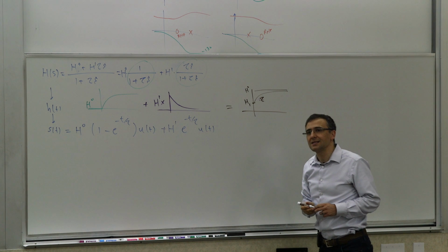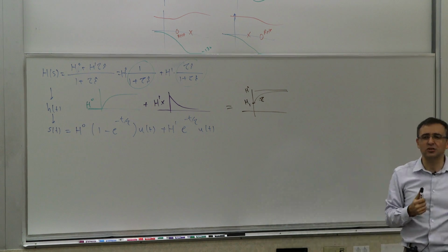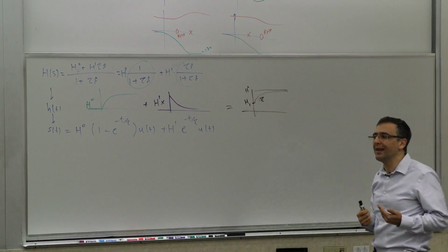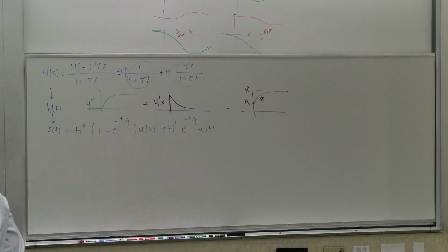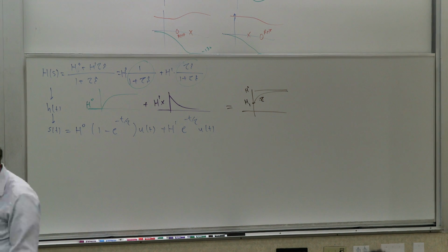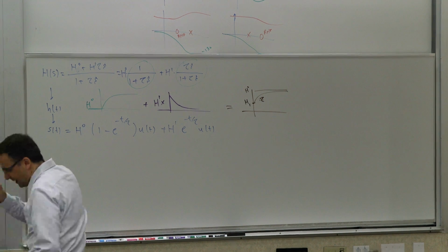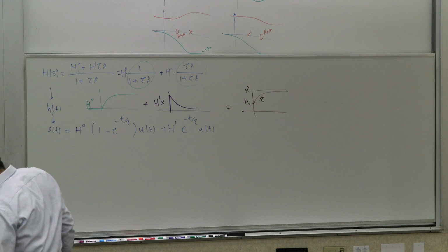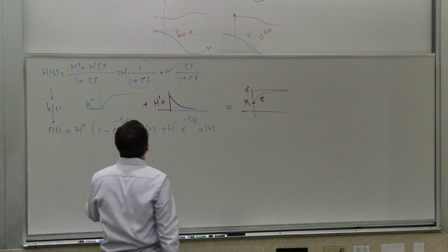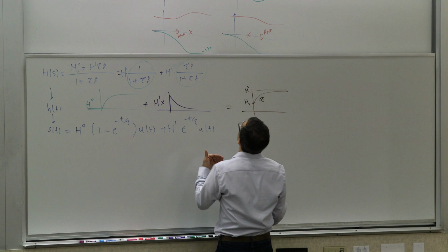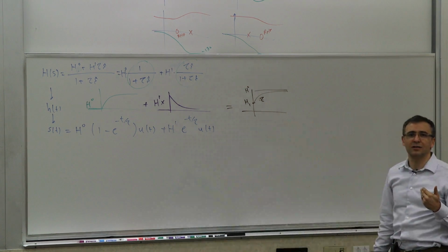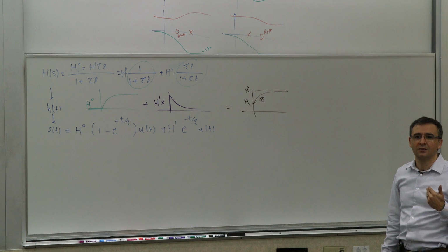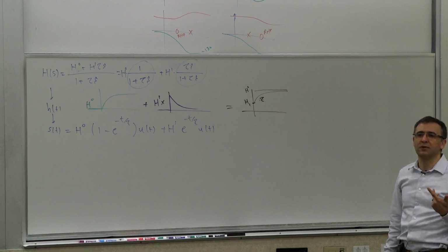If you know this, then from the relative ratio of h1 and h0 as well as the relative signs, you can come up with different types of time domain response, again by inspection. So how do we know that? For example, let's say you're in two opposite half planes, namely the polarities of h1 and h0 are different. What would the transfer function look like?